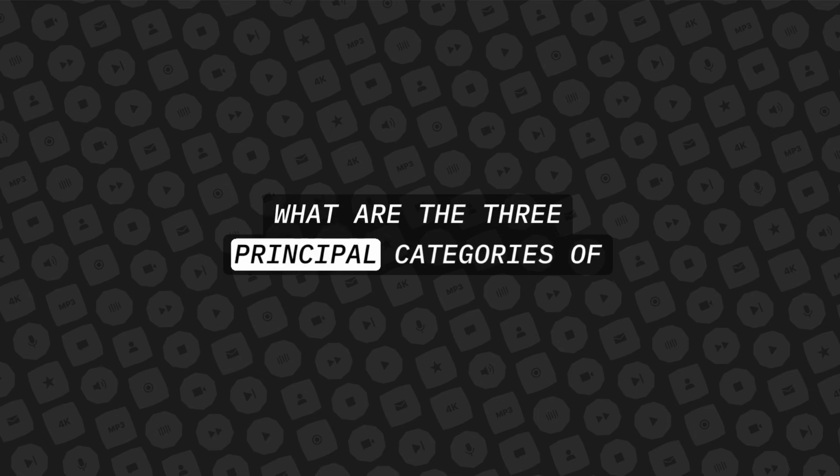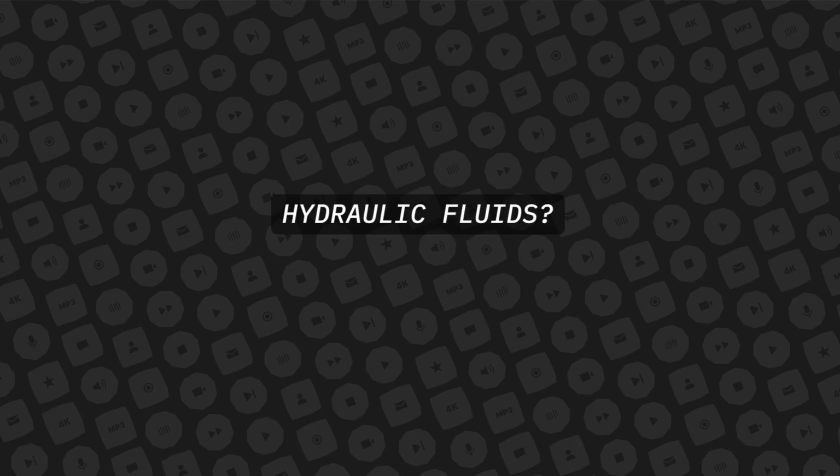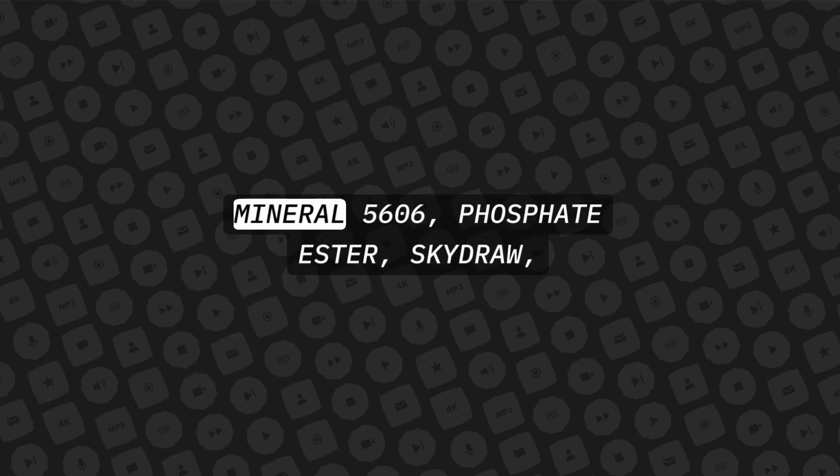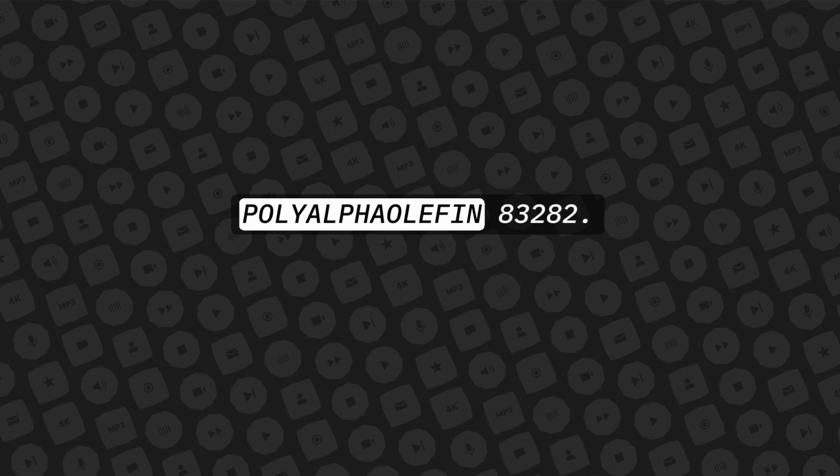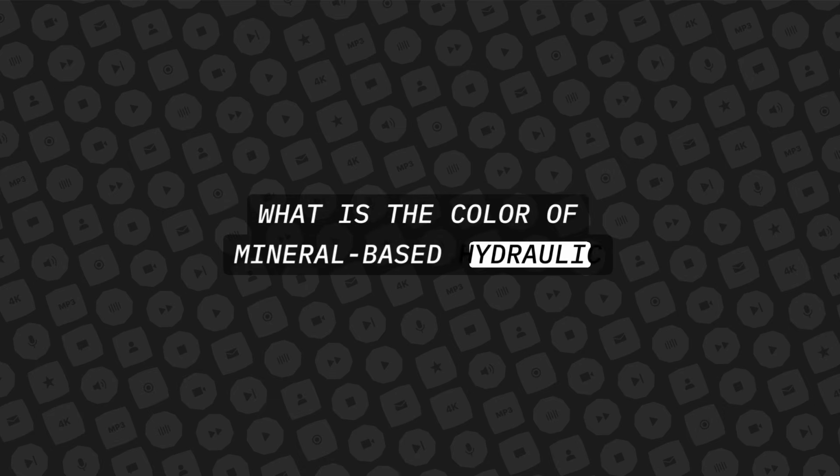What are the three principal categories of hydraulic fluids? Mineral, 5606, phosphate ester, Skydrol, polyalphaolefin, 83282. What is the color of mineral-based hydraulic fluid?